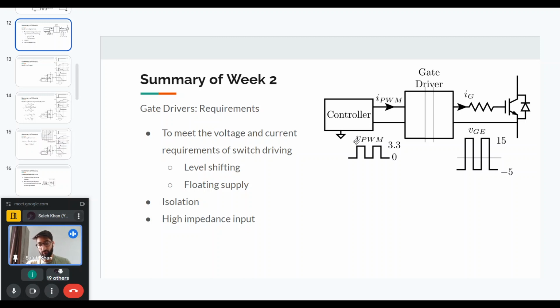So unless you have been specifically told that this is the negative voltage that is applied, I will suggest that you do not take a negative voltage randomly. I believe in the course as well, you were told that MOSFETs do not need negative voltage, and for IGBTs we usually give it, but then again, you will have to be told what is the value of the negative voltage.